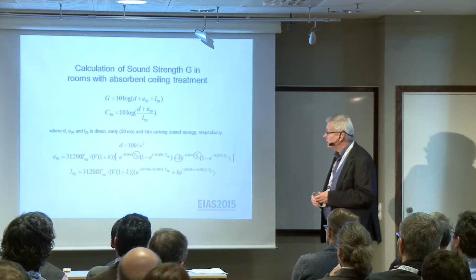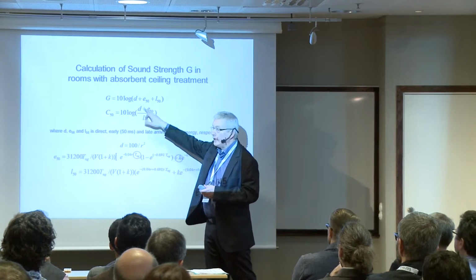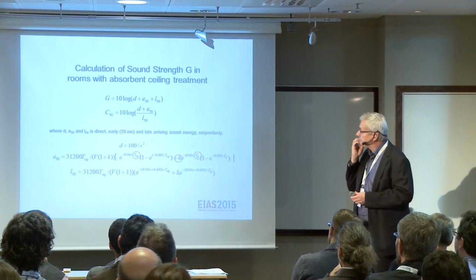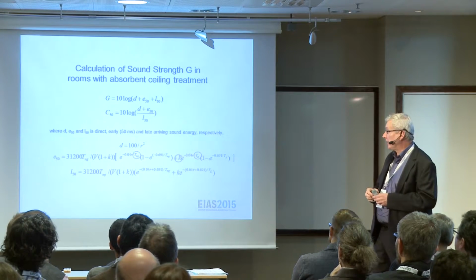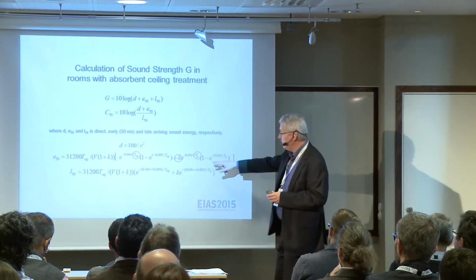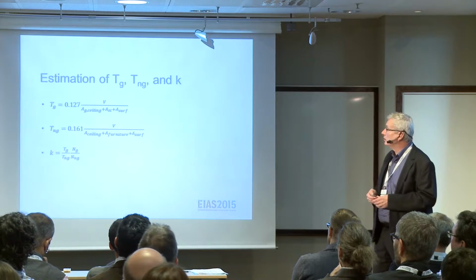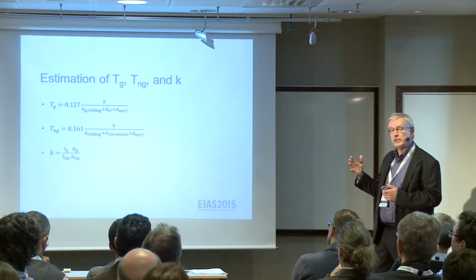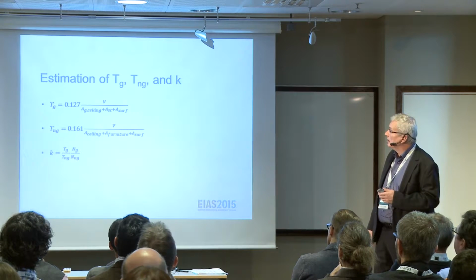But it's nevertheless quite a simple expression, and you can put them into this formula and you get the strength and you get the C50. But of course the tricky part now is to estimate the non-grazing and the grazing reverberation time and also the energy ratio. So, I will not go too much into detail, but nevertheless show you the idea of how to estimate those values.